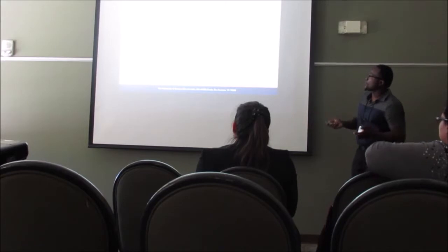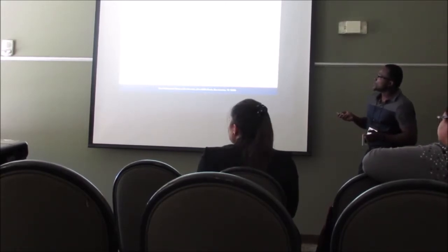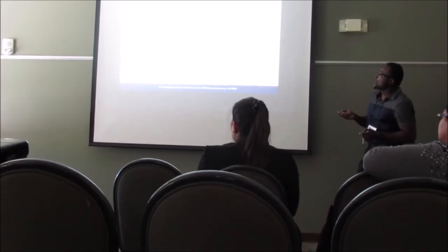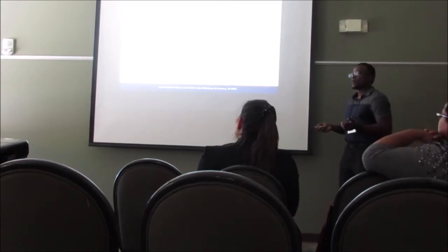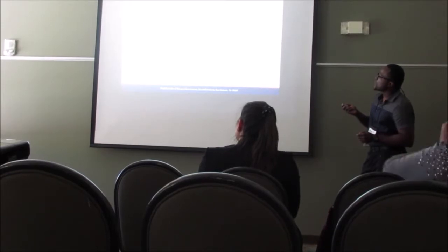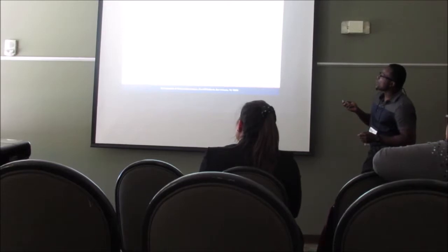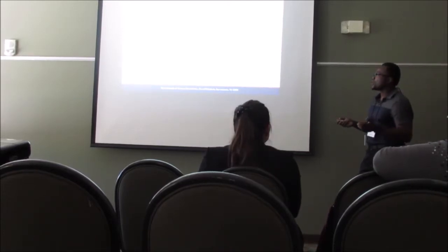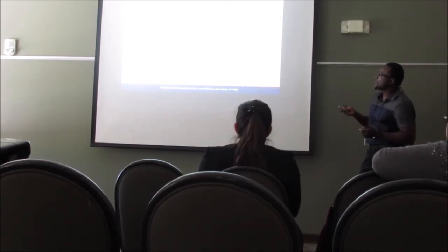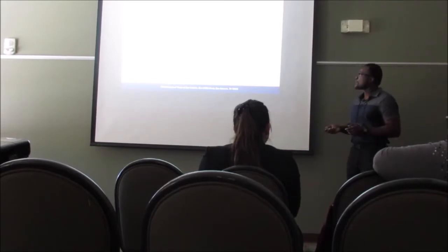So the first experimental result, going back to that graph that I showed you, if you look for the regular deformed bar that is currently used in construction, we saw that the first crack that we observed was almost around 4,000 pounds on our member. And as we kept on increasing the applied force, we saw that the bar fractured at almost 0.80, we lost 20% of the strength in the bar. And we got a good deflection, drift ratio out of it. So the drift ratio is basically a ratio of the relative deflection in the member itself.